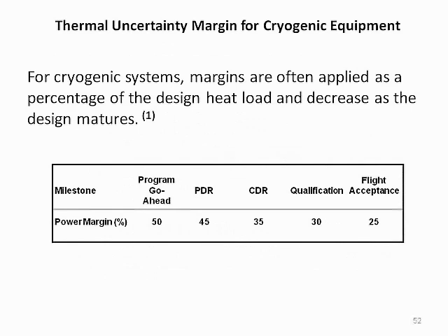For cryogenic systems, margins are often applied as a percentage of the design heat load and decrease as the design matures. At the conceptual design stage, a margin of 50% is recommended. This may be gradually decreased to 25% after flight acceptance testing has been performed.